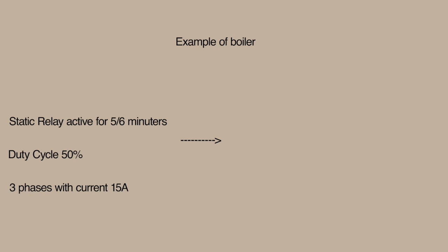The customer is using a 3-phase SSR that in full load condition will require a heat sink like our HS02. In this specific case, he has only assembled the relay on the metal plate of the cabinet. The temperature test performed on this application shows that the SSR can work without any kind of problem, absolutely without a dissipation solution. Here the cost and the space saving was as per the installation of an HS02.